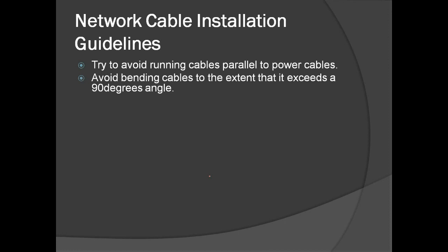Avoid bending cables to the extent that it exceeds a 90-degree angle. As much as possible, do not bend your cable at a 90-degree angle, para hindi siya basta-basta maputol sa loob. So as much as possible, avoid exceeding the 90-degree angle bend on your cable.